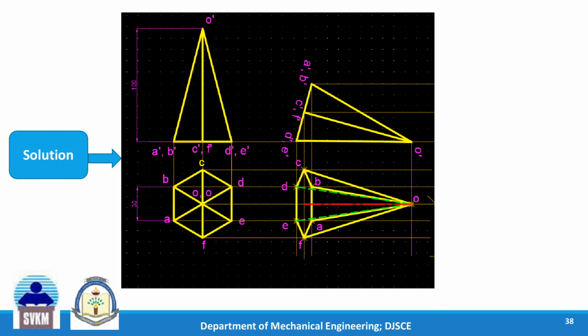In step 2 we are going to tilt so that this triangular face here will lie on HP. So when we tilt it, keeping this DE on HP, this DO will be brought in line with HP.